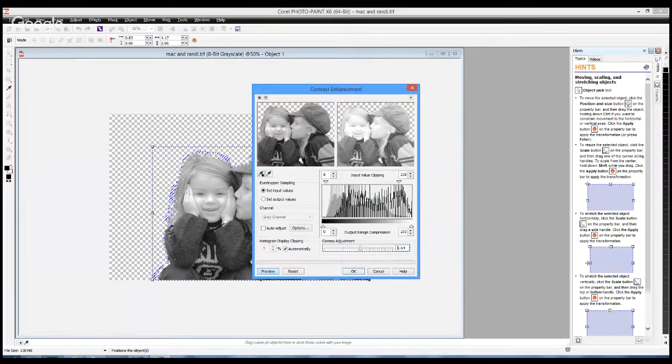If I'm putting this on wood, I'm making a higher adjustment than if I'm doing this on anodized aluminum or a material like that, where I'm not getting as much of a black image. And you'll see a little bit of different engraving qualities when I engrave this in acrylic versus wood. So always very important when you're practicing photos and trying to perfect your trade is to do the photo, make the adjustment, and then try the same photo on different materials at the same power and speed, and just see how the photo looks on that different material.